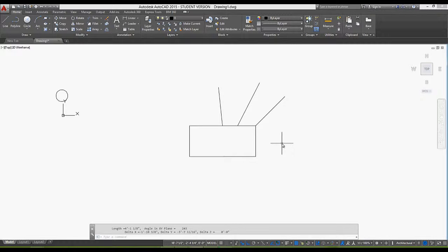So you can start to double check the properties of the lines. Now, this is going to be helpful for when you actually start to work on your homework in order to double check not only the measurements of the objects that you're going to be creating, but also the distance between them. The distance command differs a little bit in that it actually acts as a ruler. So if I type in DI for distance, I can actually specify one point and another, and it will tell me, either down here or by my cursor, what that distance is.